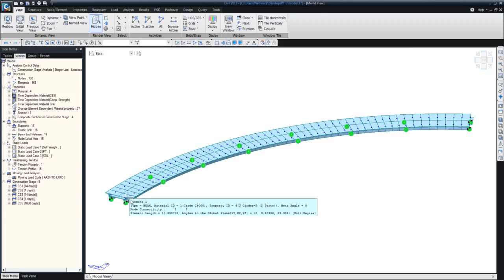And for concrete bridges, I would not recommend you to use plate elements for webs and all, because there is hardly any out of plane bending occurring in concrete thick girders or concrete webs. They are not like steel plate girders, where that phenomena is quite important. So if you are modeling a steel plate girder bridge or steel box girder bridge, then modeling everything with finite elements makes sense. And when you are doing that, then you will not be needing dummy elements, because then your deck will also be with plate elements. I hope that answers your question.